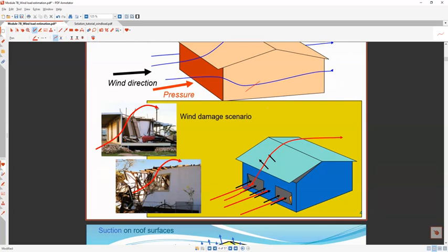You can see some other things. I'll also tell you another important thing. When the roof fails, one of the important things to think about is the connections. Connection means that this roof is connected to the purlin, to the bolts and other things. Now, if any of these connections fail, that is very problematic.